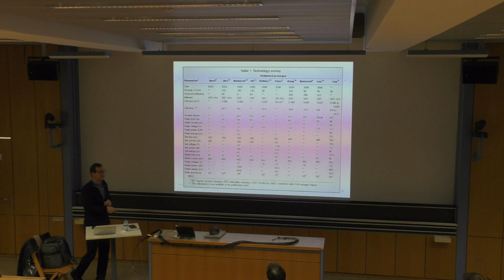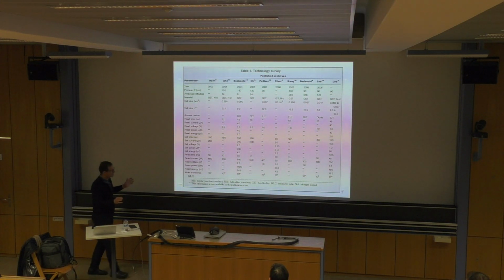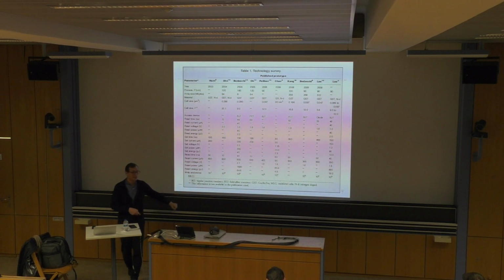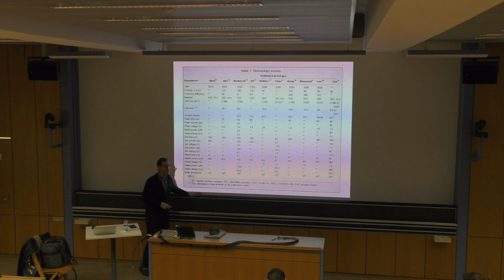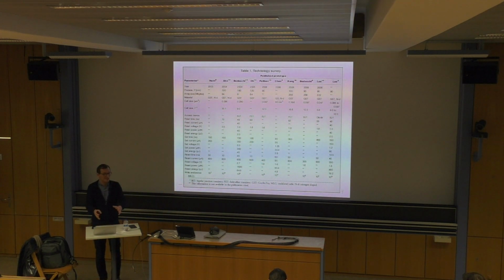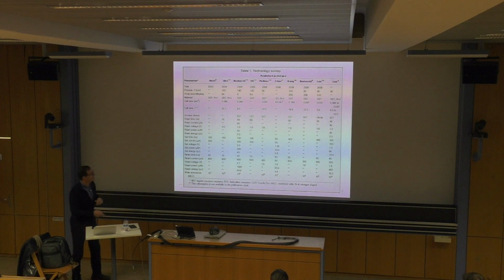That's important. This basically says how many times you can write to a cell before the cell goes bad. On average, at least. You can see the numbers are relatively small. Some of them are 10 to the 4. The best one is 10 to the 9 over here. And 10 to the 9 is not a lot. Right? 10 to the 9 is, how much? It's a billion, right? 1 billion basically. And you can easily do 1 billion writes to main memory very quickly. Okay, so we have problems with the technology, as you can see over here.